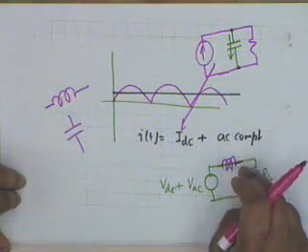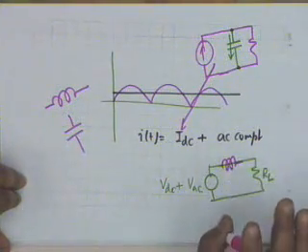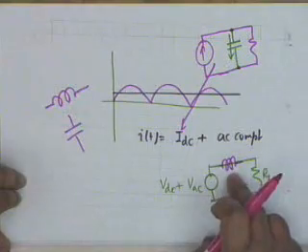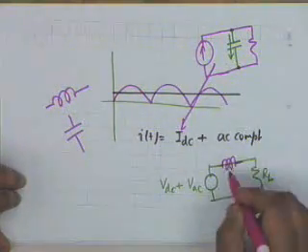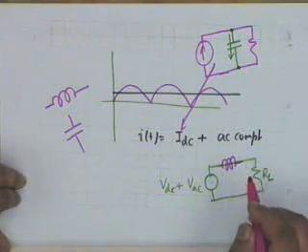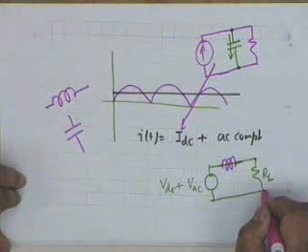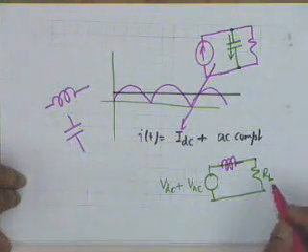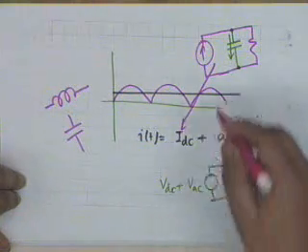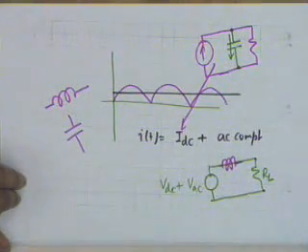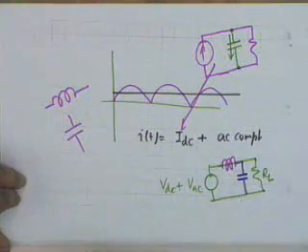Isn't that right? The voltage across the inductor is L di/dt. So as far as the DC component is concerned, d/dt of I DC is equal to 0, and therefore an inductor does not drop DC. So the DC shall be dropped across RL, and it's the AC which shall be dropped in the inductor. A better structure would be you use an inductor as well as a capacitor.